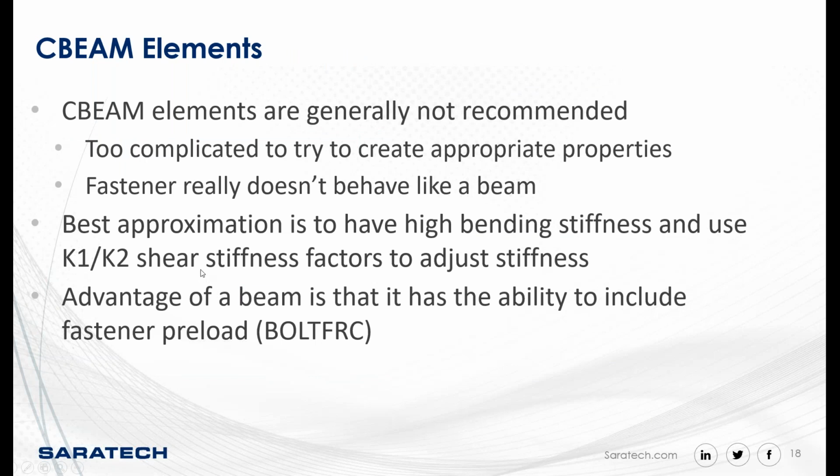And then finally, there's the CBEAM elements. Now, some people love CBEAM elements for fasteners. As I mentioned, the Rotem method is kind of dependent on using beam elements. But it's kind of complicated to create the appropriate properties, and in reality, fasteners don't really behave like beams.